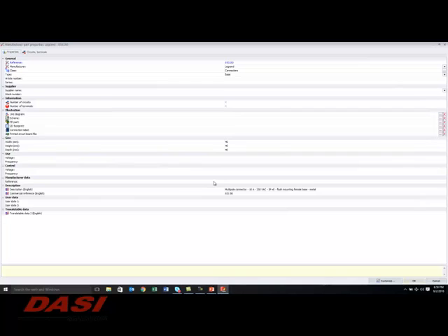So I've got 40 fields that I can use. I can use it for creating that spare part because I can just say user data 1. If I say spare part here, I can put it over here, and maybe I put 1, maybe I put 2, maybe I put 6 months repair, or every 6 months replace. I can put extra data in these areas that now will signify that if that column has something in it, I'm going to create a report for it.